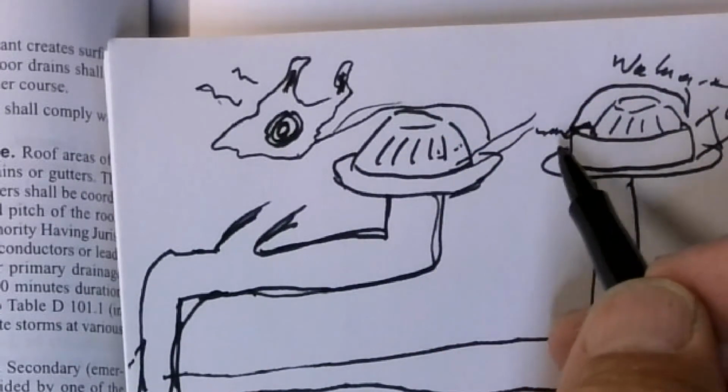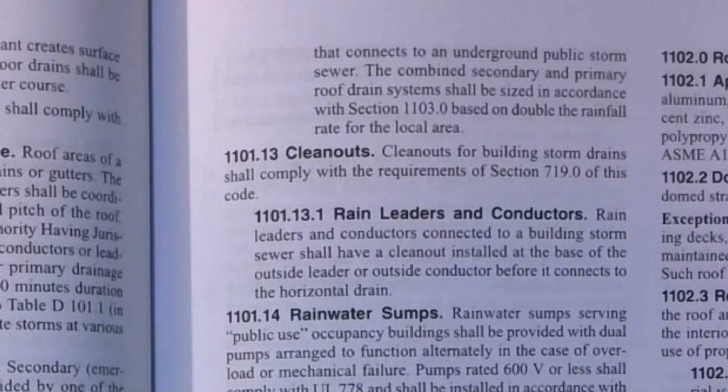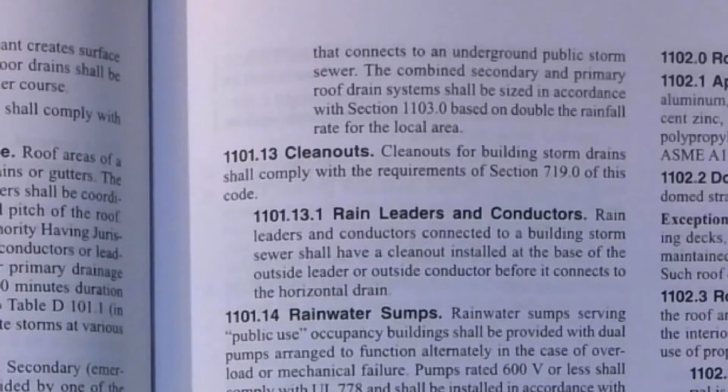The worst part about this is by the time you get to the roof, if the parapet's 5 feet high, you're looking at 2.5, 3 feet worth of water in the corner of the roof. Believe me, that roof is not designed to withstand that much weight. Have you ever tried picking up a 5-gallon bucket of water? It's heavy, okay? It's very heavy. Multiply that, okay? It's not safe. So I don't like the combined system, okay? I just don't. I don't like it at all.